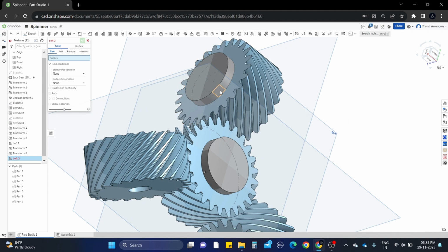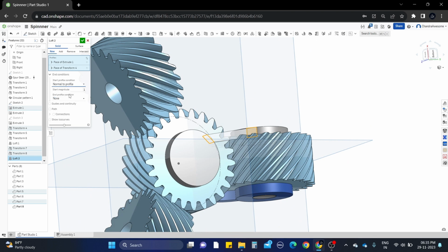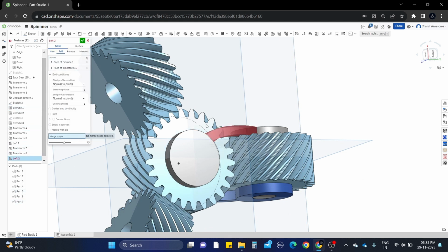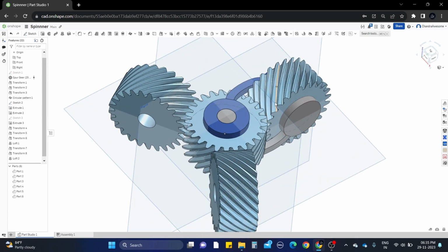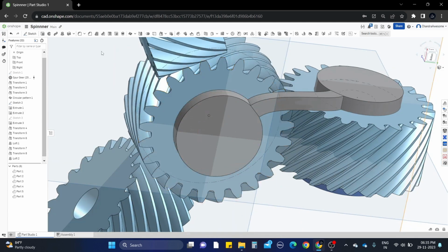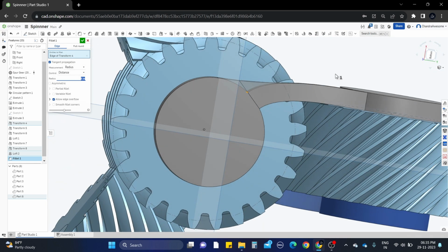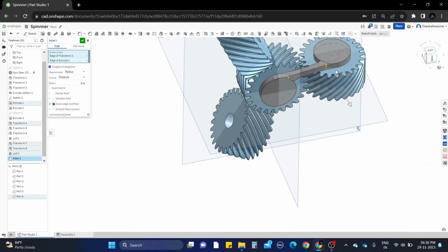Now let's do the loft operation again. Do the loft operation and give end conditions as normal to profile. And press OK. So make sure it matches with the connected parts. Okay. So what do we do now? Let's fill these gaps with 0.5 so it will look straight. Let's give 0.6. Yep. Do the same as well on the sides of both parts.